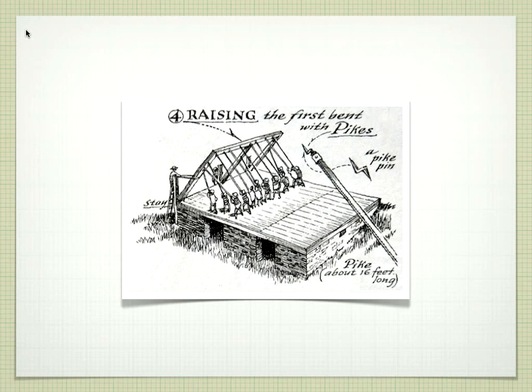So think about the labor that's involved in doing something like this. This is not something that you and your crew of two guys can do. You need more labor. You need all the neighbors to come over. The whole term of barn raising stems from something like this, where you invite the whole community over, you provide them food, and everybody helps you raise these into place, because you need that kind of labor. Notice you have somebody over here helping to lift it that way. And you've also installed what are called stays, which are temporary boards on the outside of the building, such that when you push it up into place, you don't accidentally push it too far.